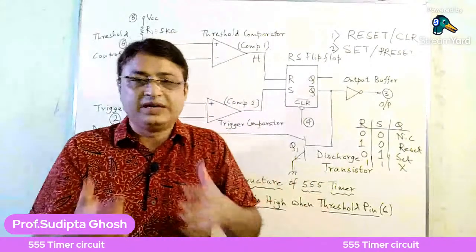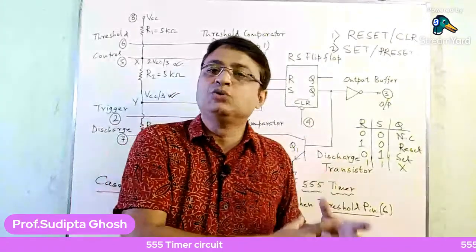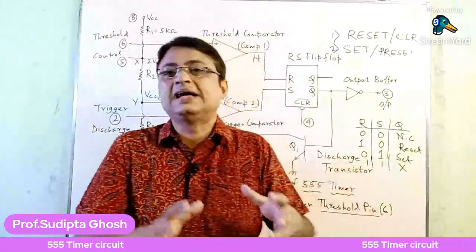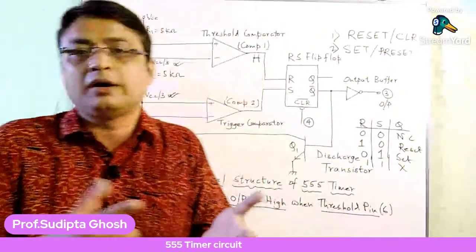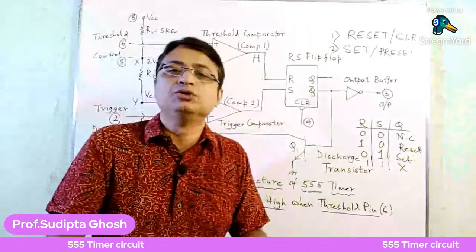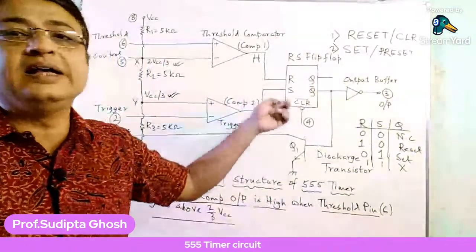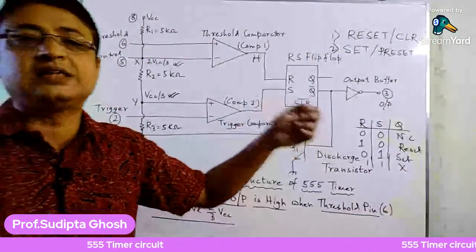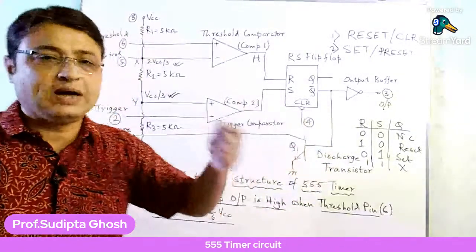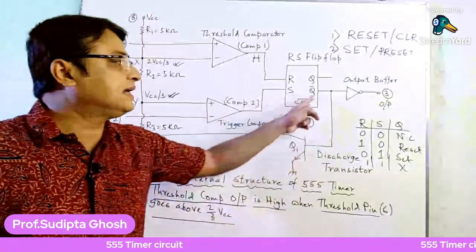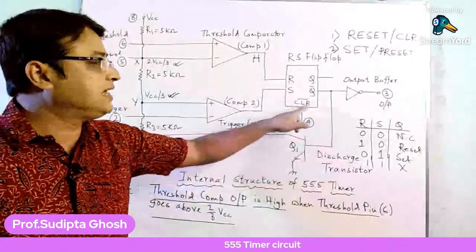also means 0. Reset means you have made the IC go to its initial value. So that is the idea behind the names: either set or preset, or clear or reset. Here the term clear is used, actually by using this particular terminal. And one thing should be mentioned here: the clear input has a bar. You can find it, CLR bar.